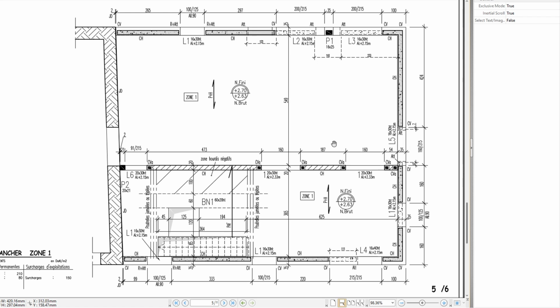And the reason I've chosen this is because this is actually an insulated concrete formwork, so it's an ICF building. And that means that there's the added complexity that it's not a normal standard way of constructing, so I can't immediately see what each of the notations here mean. And in particular here we've got the CH and we've got the CV, which I want to know what those are.